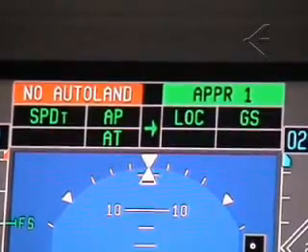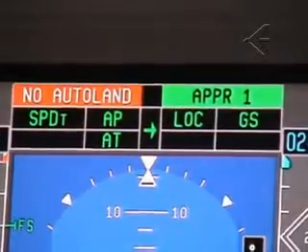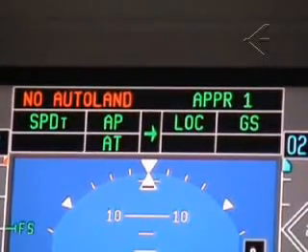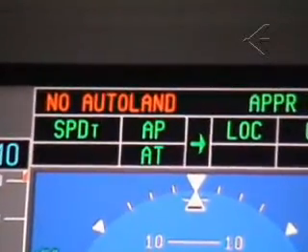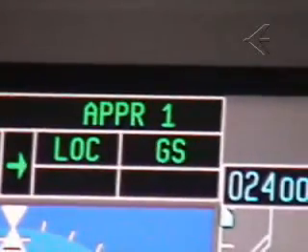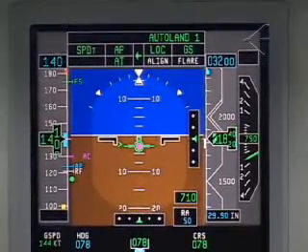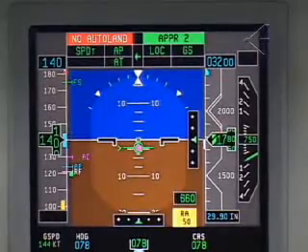Loss of Autoland engagement results in a red No Autoland flashing annunciation and a No Autoland oral warning in cases where the autopilot remains engaged. This will cause the Autoland modes, align, flare, derotation, and rollout to be removed from the armed active FMA fields. When appropriate, an amber flashing DH setting on the PFD will also be displayed.